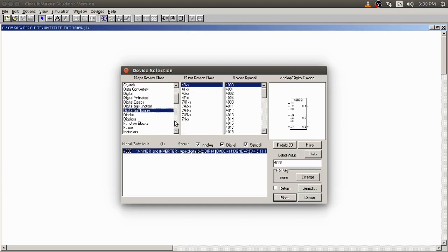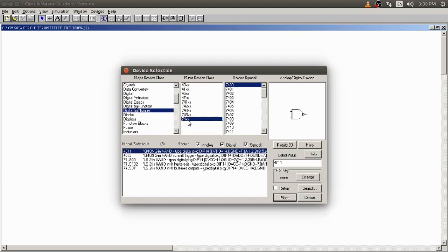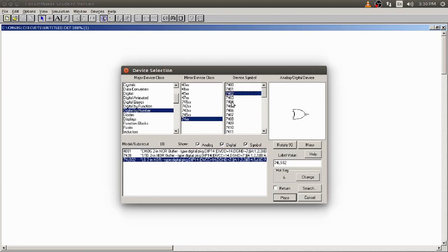There are the 74 series ICs we will use, as in the basic electronics lab, that is our introduction to electronics lab. You might have used the 7400 NAND gate, 7402 NOR gate, 7404 inverter, and so on. Here we will use the so-called TTL, that is transistor-transistor logic, which comes under this 74 series. And today we will actually use an interesting thing